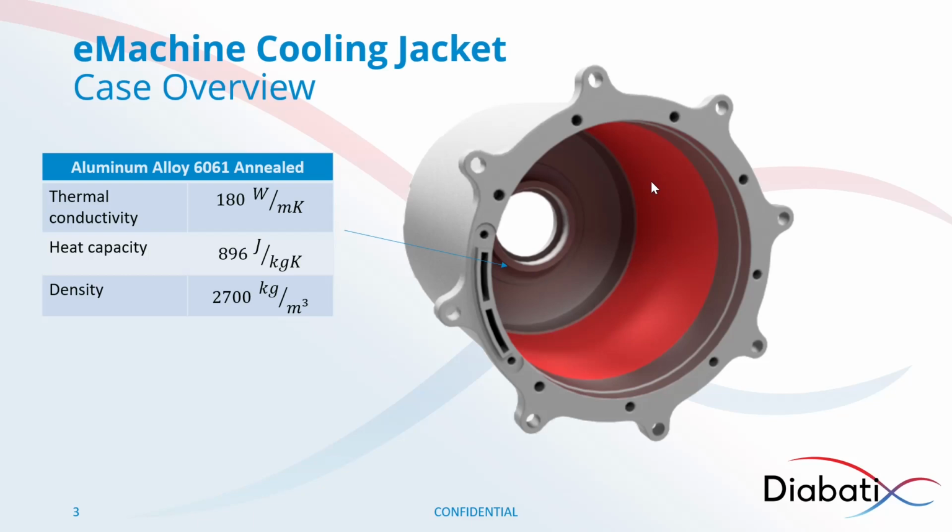We haven't modeled the entire electric motor, even though you can, because from our perspective it feels like overkill. Instead, as a replacement for modeling the entire electric motor, you can create a heated wall boundary inside this cover where your electric motor will sit.